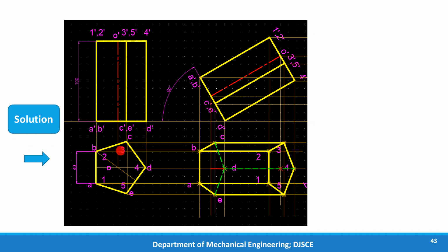We have taken the projections from the first step top view, we have connected the points. We have seen it from this side to connect the points, and the second step top view is completed. Now third step we will reorient this so that the top view of the axis is here. This point to this point is the top view length of the axis.